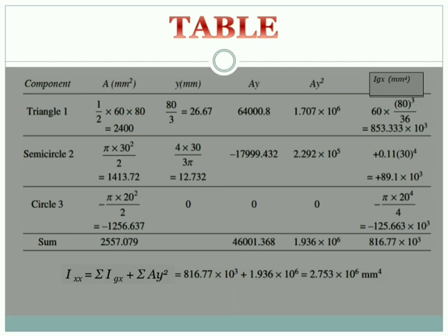Now in both the cases which I solved, the given axis was horizontal. Similarly, you can get a problem where the given axis is vertical and we have to find the moment of inertia of the given figure about that vertical axis. So in that case, what all changes? The first area column remains as it is. Then instead of y1, y2, y3 and so on, we will be calculating x1, x2, x3. Next column will become Ax. Next column is Ax², and the last column we'll have is Igy instead of Igx.